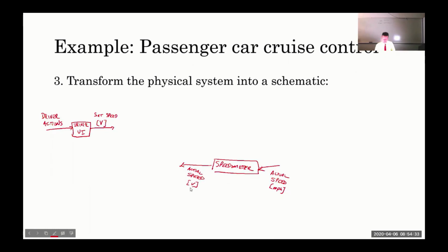But now measured in volts. Okay, so that's a non-trivial operation and often gets overlooked. Because, so you buy a speedometer from company A, and it might have that 60 miles an hour corresponds to 3.4 volts. You buy a speedometer from company B, and all of a sudden it has a gain that says 60 miles an hour is 10 volts. Those two speedometers are not interchangeable unless you were to then change what comes downstream, okay?